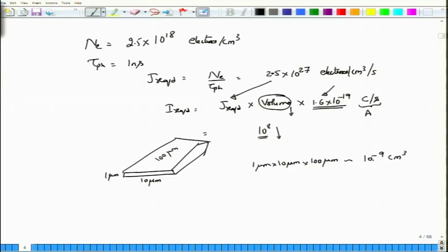Okay. So, when you now substitute this 10 to the power minus 9 into the volume here, what you get as the required current will be about 0.4 amps or 400 milliamperes. Now, this 400 milliamperes is quite manageable. Most laser driver circuits will offer 400 milliampere without any problem. Some laser drivers also offer 1 ampere of current if you wish, and those are really the high power lasers. So, for most communication laser purposes, 400 milliamperes, in fact this 400 milliamperes is according to an older technology.